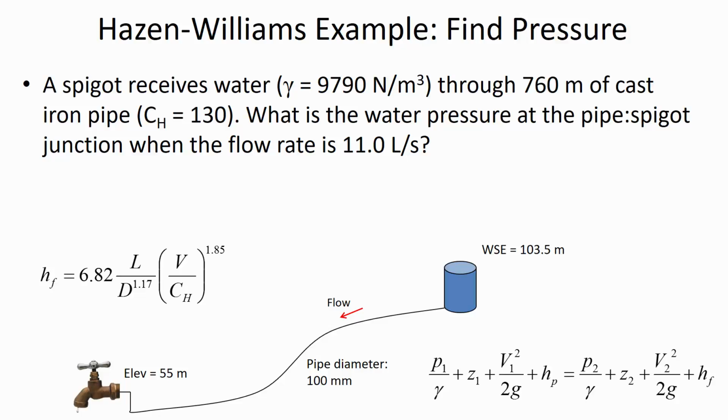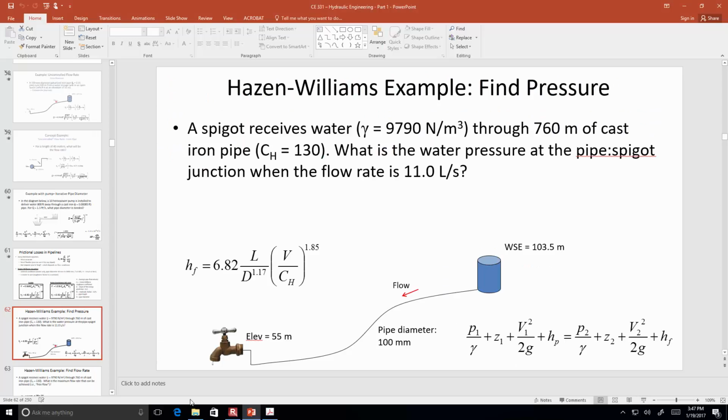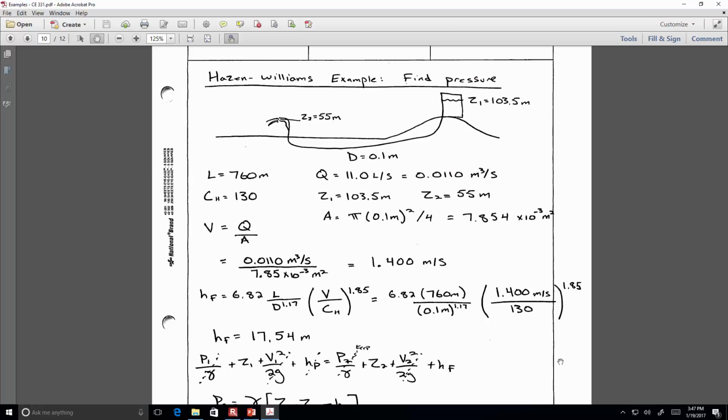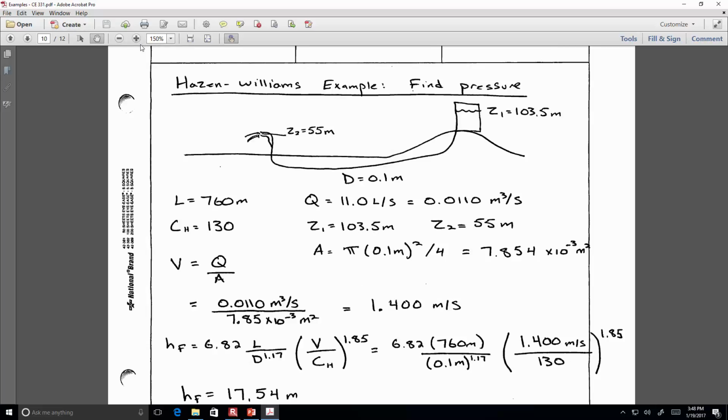The energy at this tank, at the origin, is potential energy, and it's causing pressurization downstream, and it's also giving up energy to losses. And what the Hazen-Williams equation, which is shown here, helps us to calculate is the losses side of things in an easy, direct way. And so when you substitute in the velocity, let's see, I think the velocity you should have calculated is 1.4 meters per second. Is that right? All right.